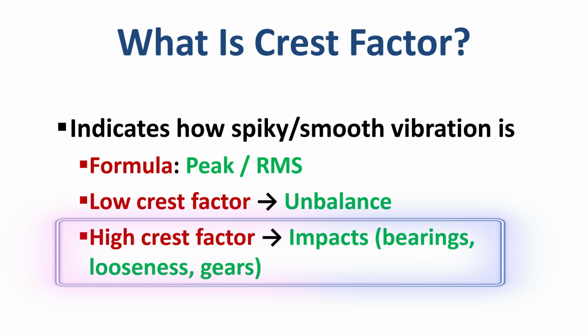Whenever we have a high crest factor, the most common defects are bearing defects, or some kind of mechanical looseness, or gear defects, or defects related to some kind of impacts. This can be a cracked or damaged bearing also, right?